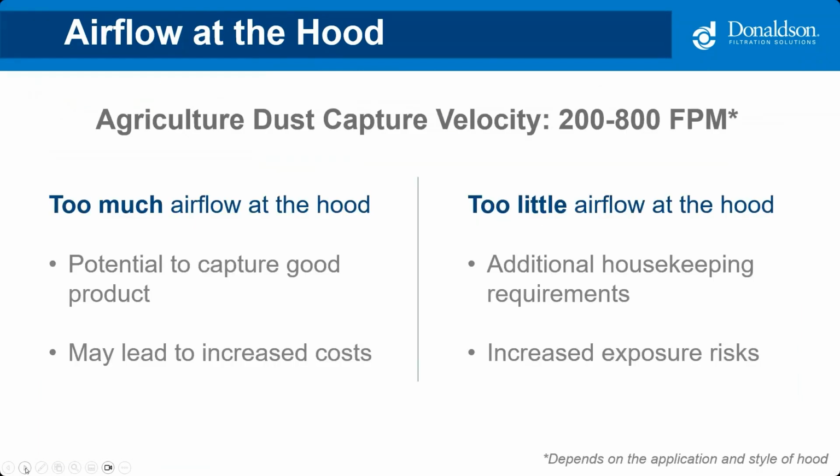When you're designing hoods, you want to avoid airflow extremes. With too much airflow at the hood, you've got the potential to capture good product. It also increases your cost because it's going to require more static pressure to move that air. And with too little airflow at the hood, we're not going to be able to collect the dust itself. We're going to have additional housekeeping requirements, and then of course increased dust in the facility.